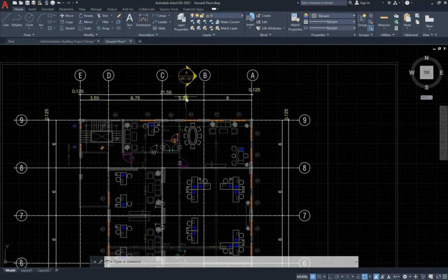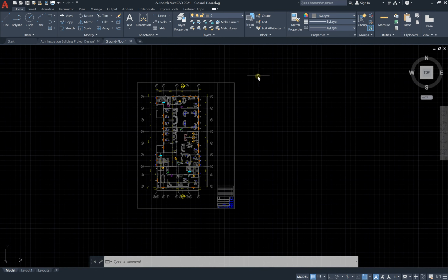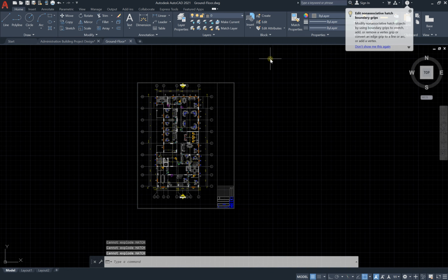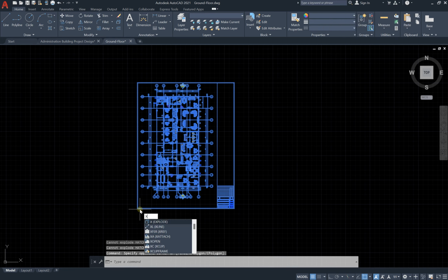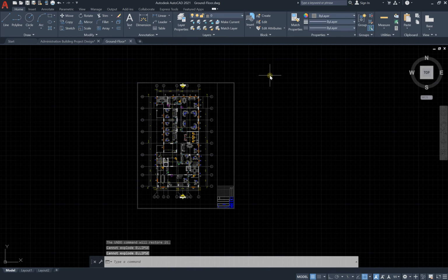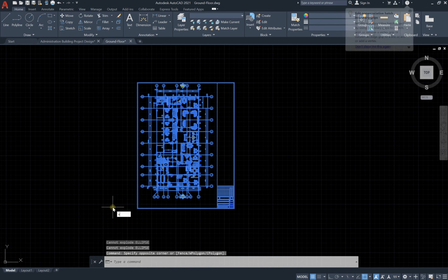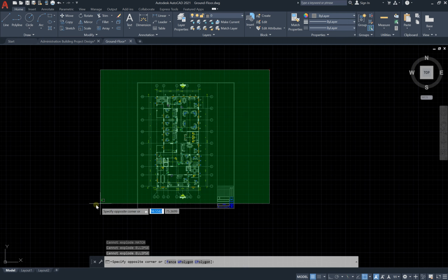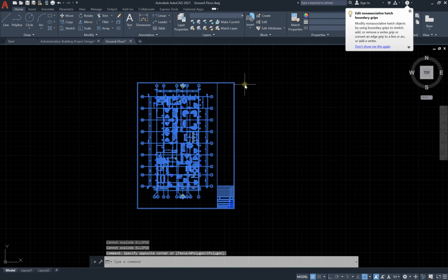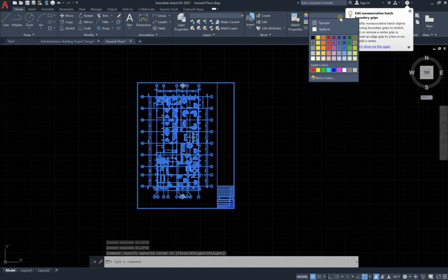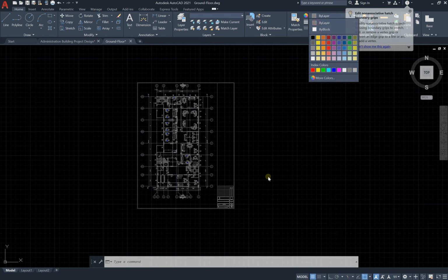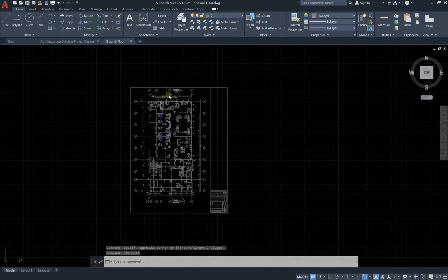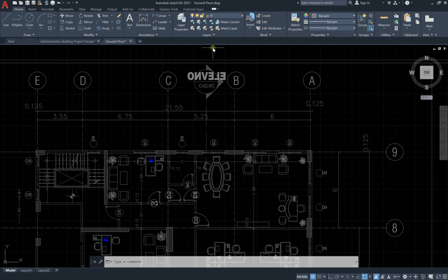So what you are going to do is simply go like this and explode like this, okay, several times. Explode like this, okay, like this, okay. Let's say 3 times, because there are some blocks which are inside other blocks. And then click on them like this, okay, like this. And you can even change it here by layer like this, and skip like this. Now let's see. You'll see that these colors change into gray, right, as we have just seen.